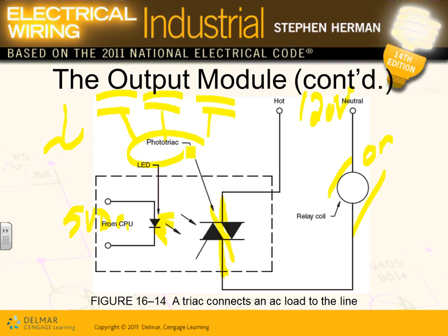Here's my contactor, and you can run a 300 horsepower motor. You see that little coil, a 120 coil they close from the PLCs? Now, this coil will go bam, bam, bam, shut this contactor and start a 300 horsepower motor. And all came from what? 5 volts coming from the VFD, converted into a light, picked up by this triac, closed, bringing the 120 into a coil. The coil is energized, and the coil will drive these contacts to shut.